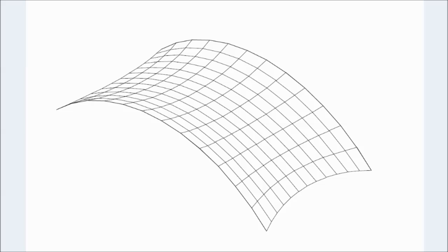In this video, we're going to learn several simple ways to make careful estimates that will enhance our understanding and use of FEA. Let's spend a moment talking about how a tensile structure reacts to loads in general. As our model for this discussion, we'll use a simple 120-inch by 240-inch barrel vault roof between two arch supports with cables on the bottom edges.